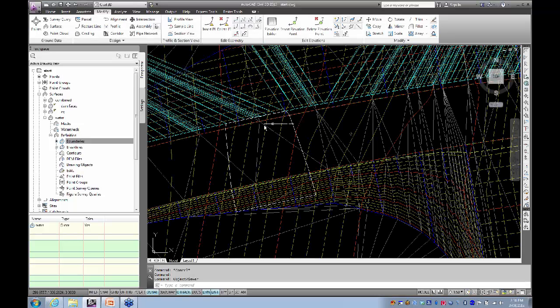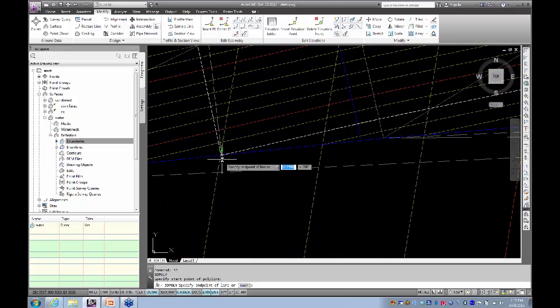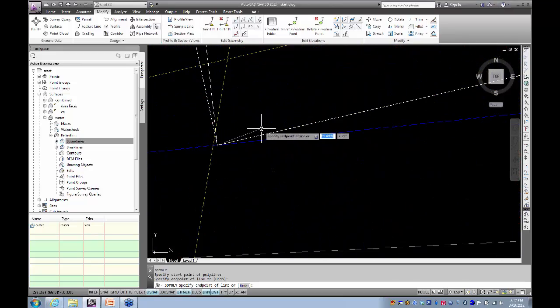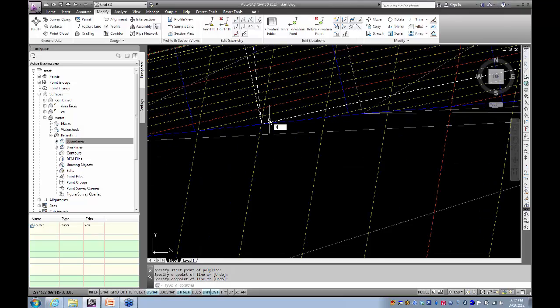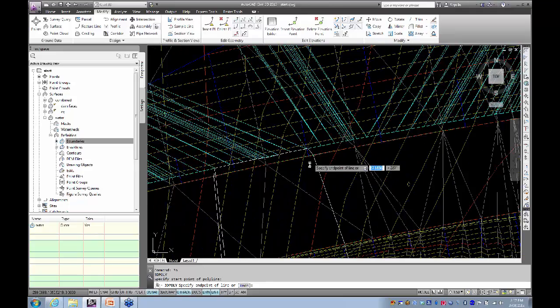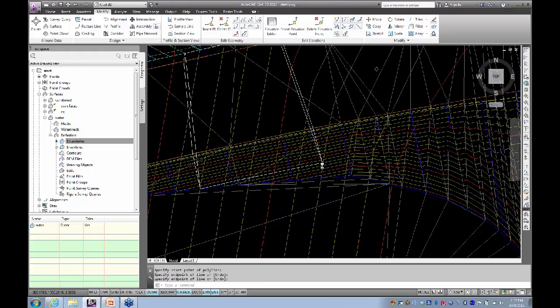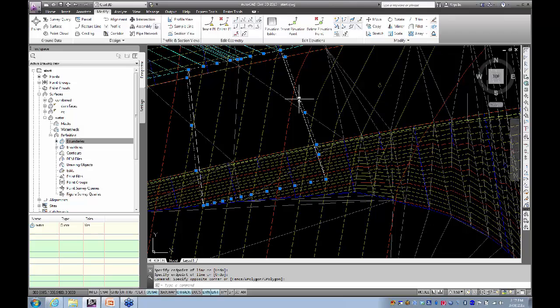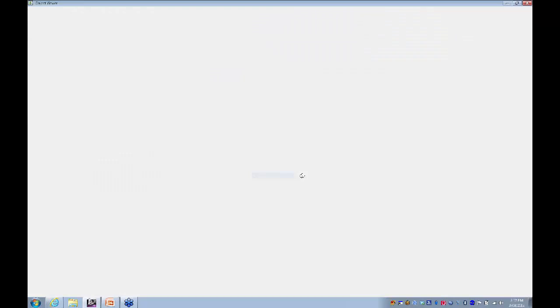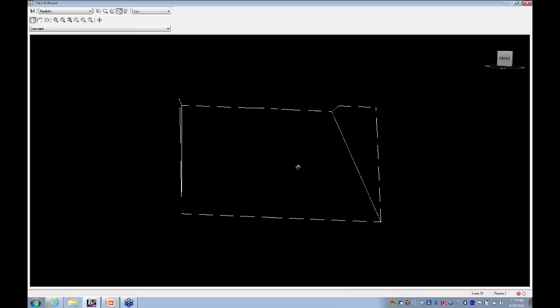So I'm going to close that off and just do 2 more 3D polylines, 3P. In there. Just to put the bottom of my spillway walls in. Another 3P. Between there and there. Grabbing all 3 of those, I want to have a look at my object viewer again. It's a great way to check you've got it right, and that's not looking too bad.